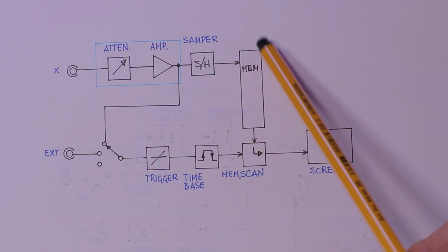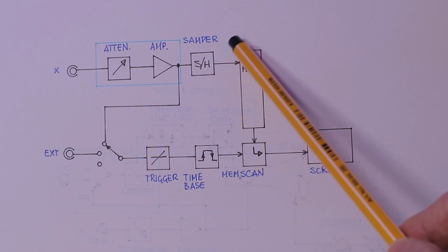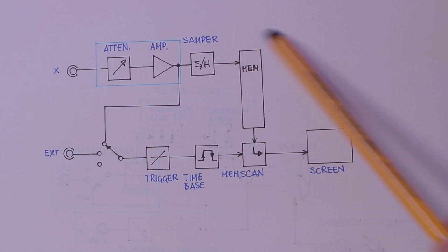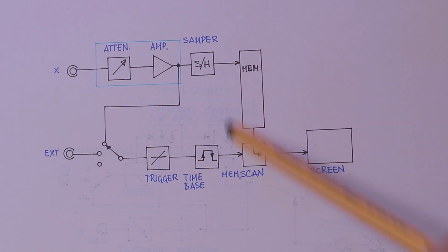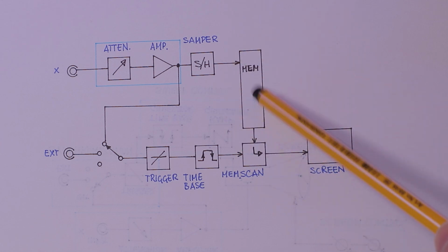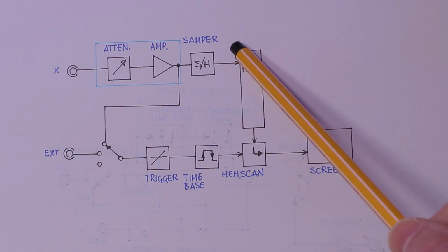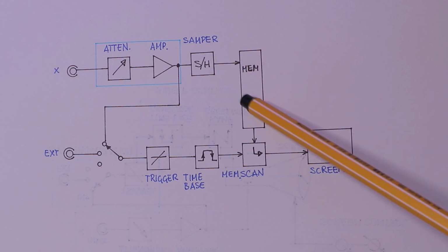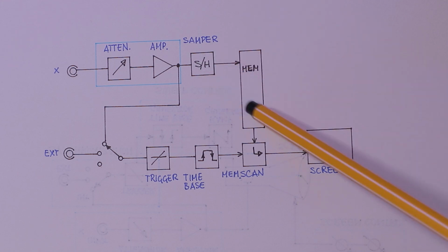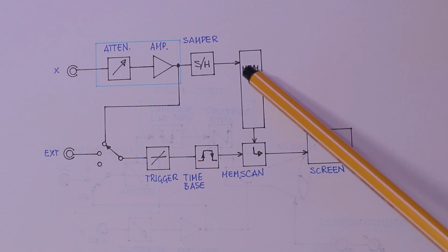as they determine the speed at which the instrument can grab the input values. It is radically different with respect to an analog instrument. The world that the instrument allows you to know is limited inside the quantization. Everything outside it is ignored. This means you may miss a sample where an actual event happened. While on analog instruments you are limited by the bandwidth and the speed of the phosphor decay, here you are limited by the quantization time and resolution. An analog oscilloscope is a tool to exploit physics to display the instantaneous amount of electric charges on a continuous line of events. A digital oscilloscope is an abstraction.